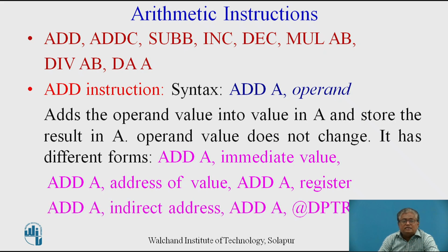This ADD instruction also supports the indirect addressing mode, and this ADD A comma @DPTR is to be used to access the data from external data memory.